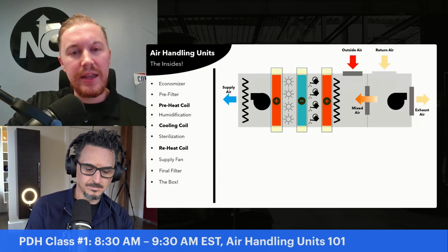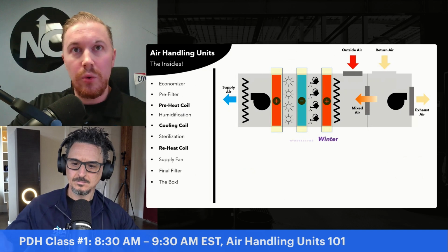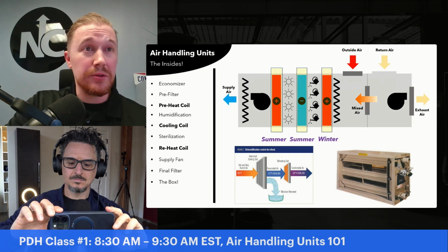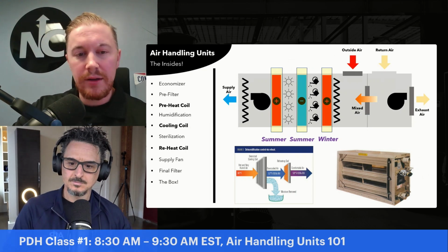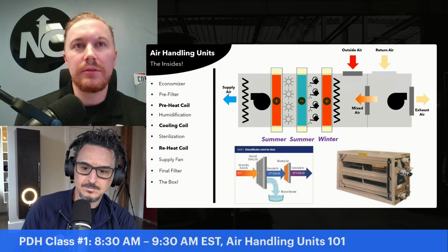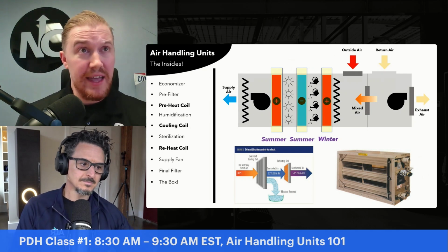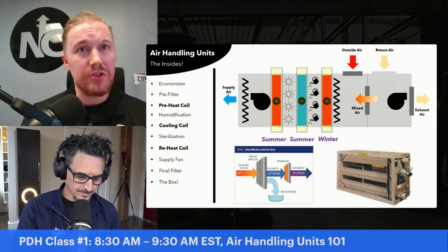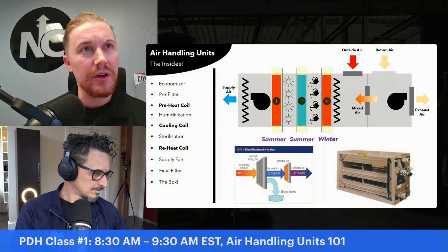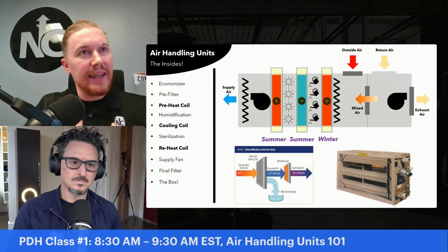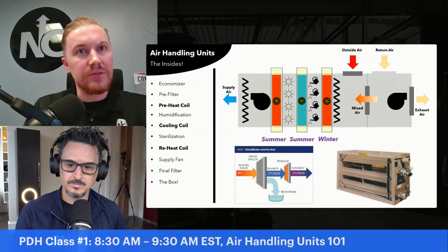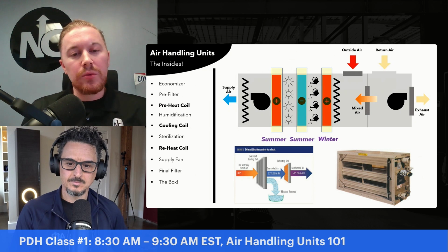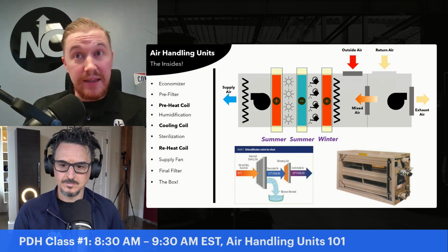Okay, we might have preheat, chilled water, and reheat coils in the air handling unit. And why might we have that, especially in a single zone unit, that reheat in a single zone unit? Well, if we look in the bottom left, we can see a little diagram of what a dehumidification process looks like. Our mixed air condition comes in, hits our chilled water coil. We cool down to 52 degrees at 95% RH, wringing out that moisture from the air into condensation in a drain pan. And then we'll use that reheat coil to reheat the air we deliver to our space for comfort